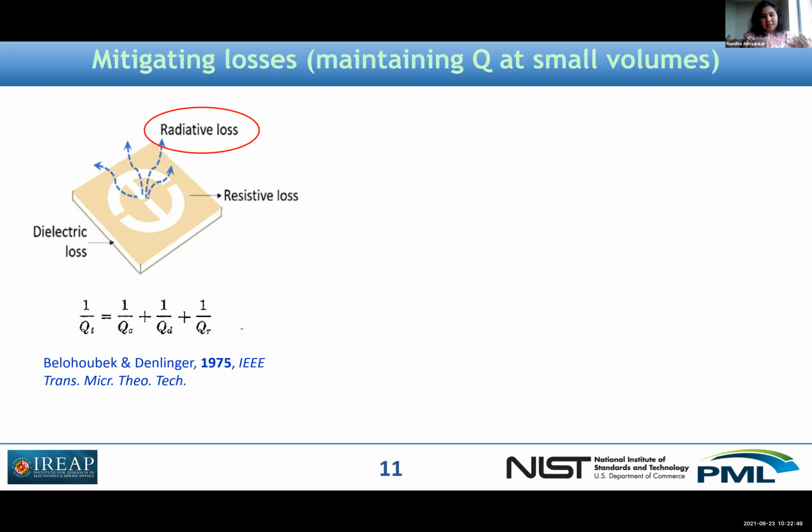That decreases the overall operability of your EPR spectrometer, because it's not very useful if you can only operate it at low temperatures. The second is the dielectric loss: if your microwave is going through the dielectric substrate, it shouldn't be absorbed in the substrate because it's lossy. A great way to overcome this is by using low loss substrates.